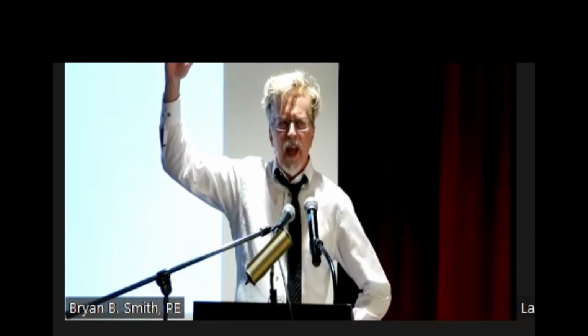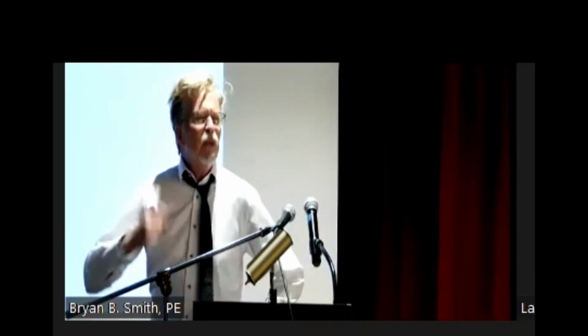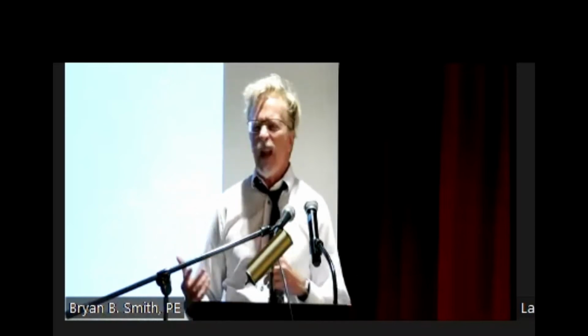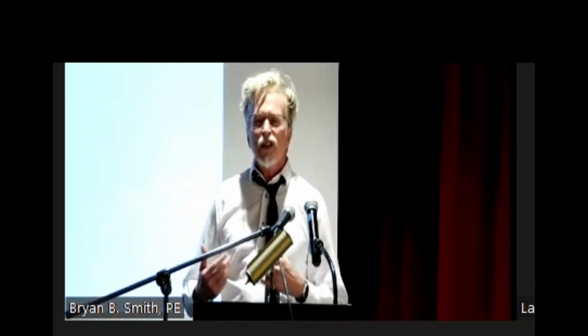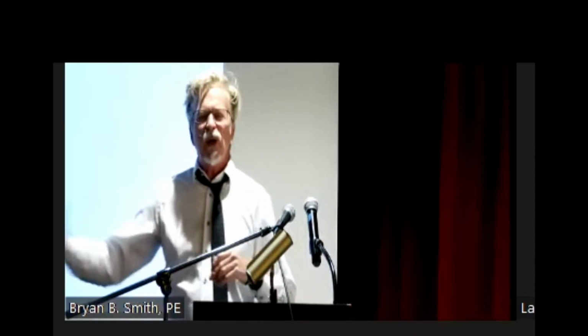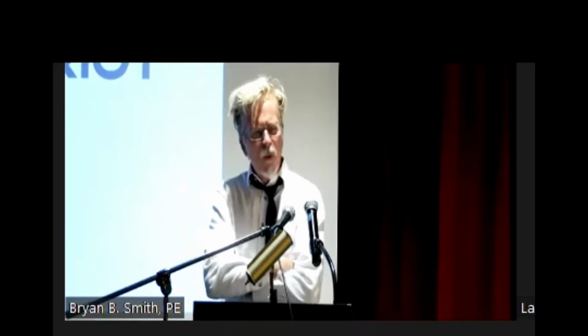Somebody turned off a pump. We have some electrical engineers here. I heard that every once in a while, there's a power failure. How many have ever experienced that power failure before? So if I'm running my pump and I have a beautifully designed system, right? Pump's designed perfect. I might even have a pump control valve to manipulate the starting and stopping of that pump in the system. And I have specific flow, pressure, velocity going out into my system. And then we lost our power. And guess what happened to my pump?